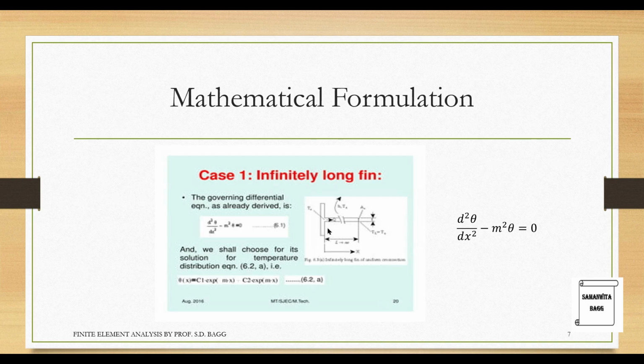As you can see here, this is a long fin. This is its governing differential equation. So we are going to use the governing differential equation. We will study its solution, and from the solution we are going to derive a particular element matrix equation that will be used for solving the problem.